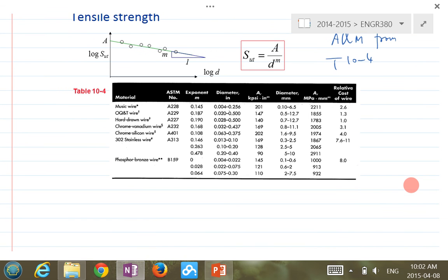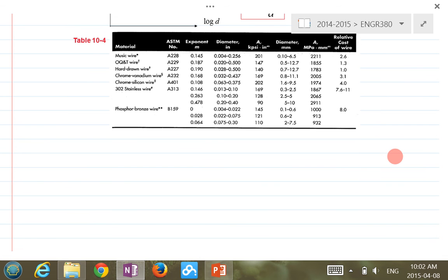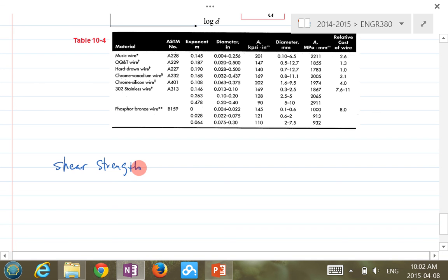But if you look at the stress in the spring, what kind of stress is it? It's a shear stress. So if I'm going to compare the strength with the stress, I don't need Sut. What I need is the shear strength. More precisely, it should be the torsional shear strength, which we call Ssy. So we need this one here. How do we find Ssy then?